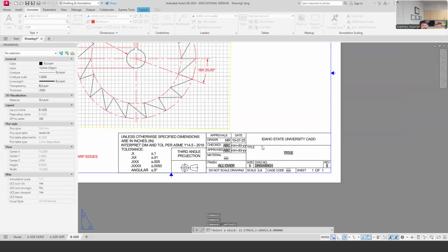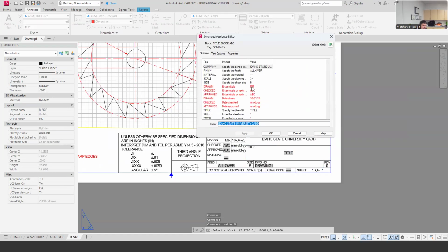Let's see. I had to put in the scale. That's really critical. Then I had to initial it because it's me doing the initial drawing, and the date. So that's the third one. The title I need to change. The title can be just, I haven't even saved the drawing number, but they can usually match, so you can just write that this is either just the ratchet plate or I usually always put the CAD. It just helps me search my files a little bit. Mine's CAD 1108, and this is a ratchet plate. I do all caps there.